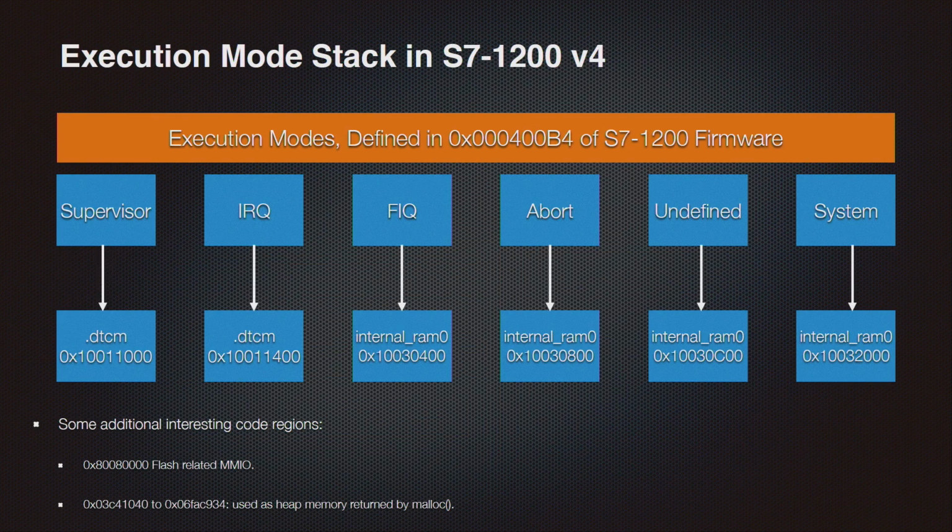All right, now we got some information about the different memory maps and address ranges which we will find in such a firmware image and while it's running. One thing that is important to know here is that for a Cortex R4 processor, which we are working with in this case, they bank, as they call it, different registers for every execution mode, and then you have different stacks for those modes. If you wanted to do forensic work or even some reverse engineering, it's interesting to know those addresses which we extracted